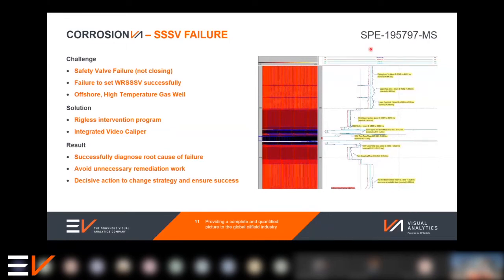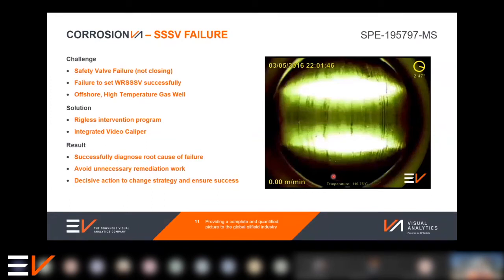And you can see here the different step changes, the different recesses as we work through the assembly. These were then matched up with an engineering drawing of the valve in question, and actually everything looked fine. The dimensions that we'd captured looked very close to those of the manufacturing drawing and were certainly within tolerance for accepting the insert valve. But it's when we then switched back to the video and looked at the seal bore surfaces in a lot more detail, we then understood the problem.